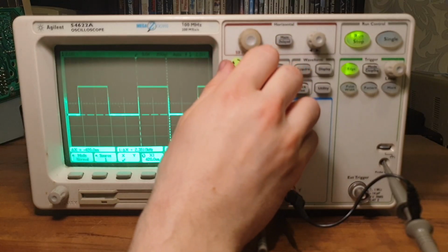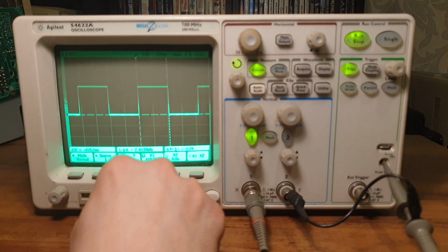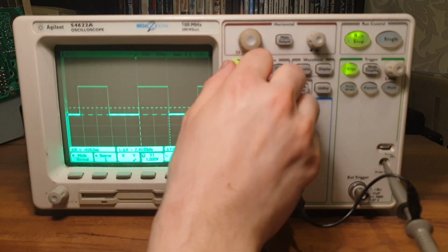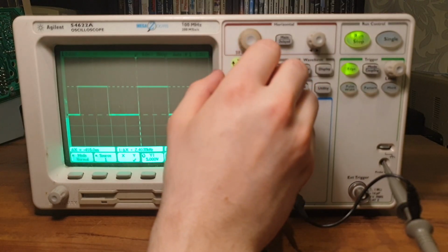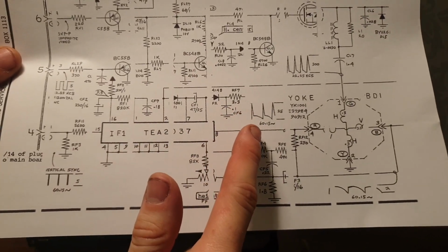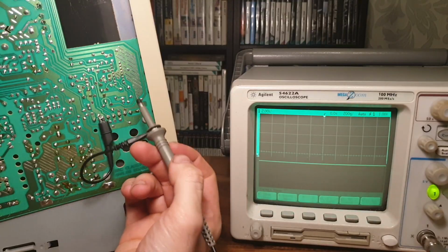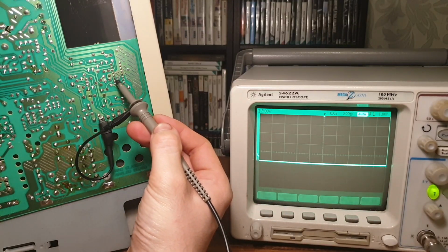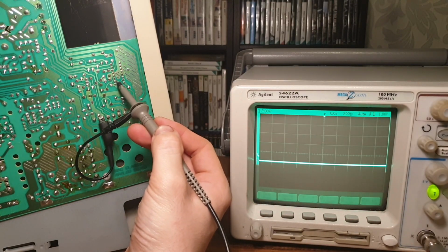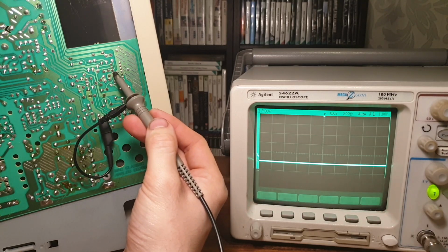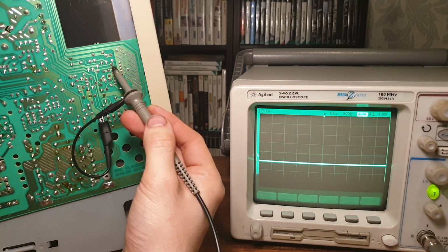Now we know what an oscilloscope is, let me explain how we're going to use it to diagnose the Mac. Essentially, if we set the controls right, we can look to see if the waveforms described in the schematic are what we see on screen. So for the vertical deflection, we need to see a 60ish Hz peak at around 25 volts on pin 8 of the TEA chip. And on the Mac we get...